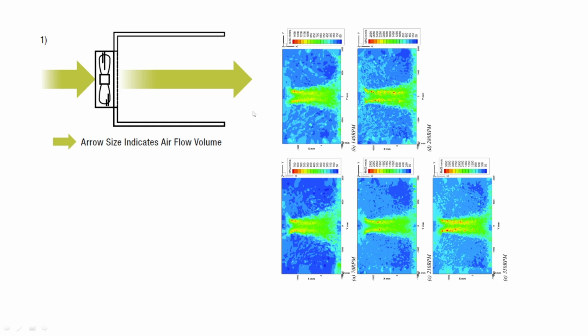So basically, I have my fan, I slap it up against a tube. The tube is the same size as the fan, and I blow air down it. Now, the reason I don't like this test is that it isn't quite representative. My fan is the same size as the tube, so there's no room for the air to spread out. A fan that has a tendency to spew air off to the sides has nowhere to send it other than down the tube.